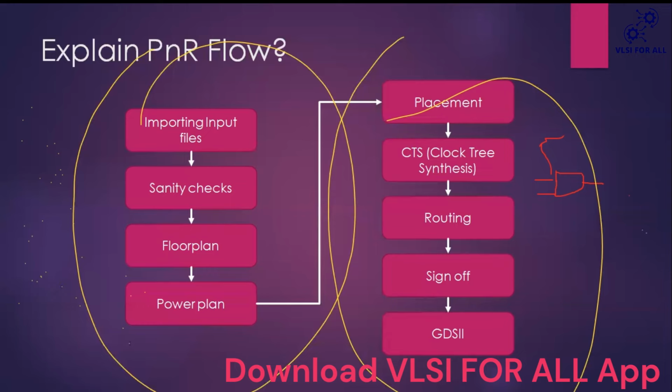Sometimes, as I said, if the design has multiple voltages, you may see power rings for each block. Most of the time, if the design has only a single voltage, you see only power stripes, S routes, and standard cells. After creating this, we move to placement. During placement, there are many steps.